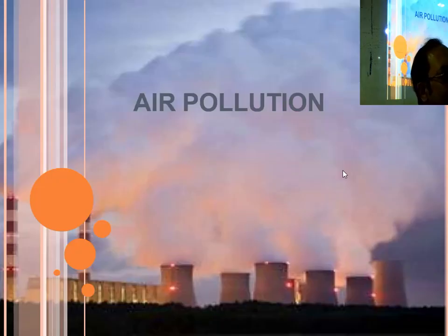Primary air pollutants are carbon monoxide, SPM, suspended particulate matter, oxides of nitrogen, oxides of sulfur, and lead. These are all primary air pollutants because there is a direct source available. And there is a 6th one, ozone, which is not directly produced and going to the atmosphere. Rather, it is produced in the atmosphere itself. That's why it is called secondary. Those having a direct source on the earth are called primary air pollutants, and those created in the air itself are called secondary. So primary 5 and secondary 1. Total 6. These are called criteria pollutants.